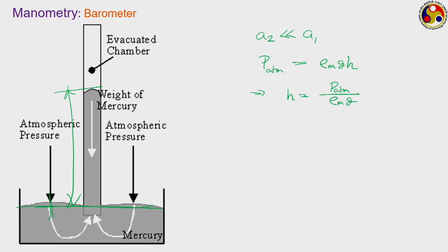Now barometers are very standard devices used everywhere in the world and for ages, and this simple relation also gives us another way of defining a pressure scale, which I have mentioned a few slides back. Now standard atmospheric pressure, as I have mentioned, P atm is equal to 1.01325 bar, or if we write in terms of pascals, this into 10 to the power 5 Pascal.